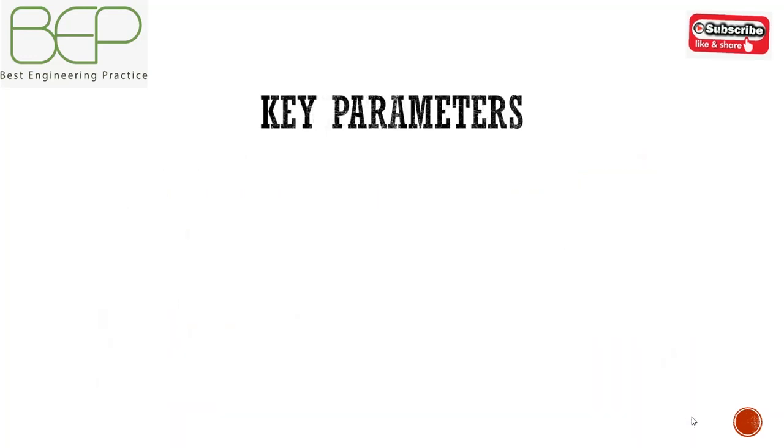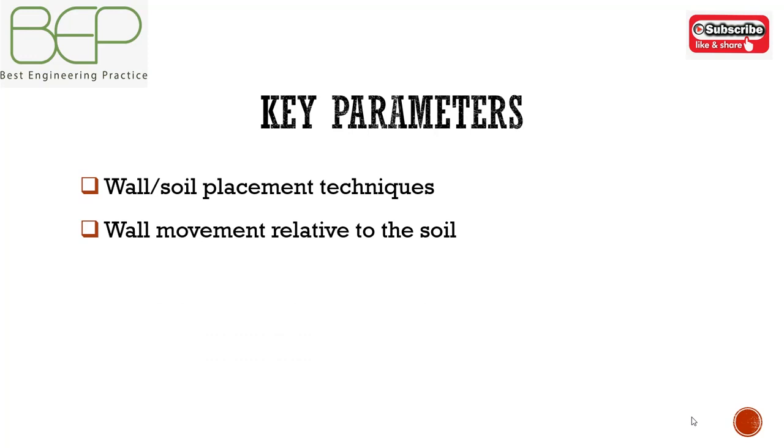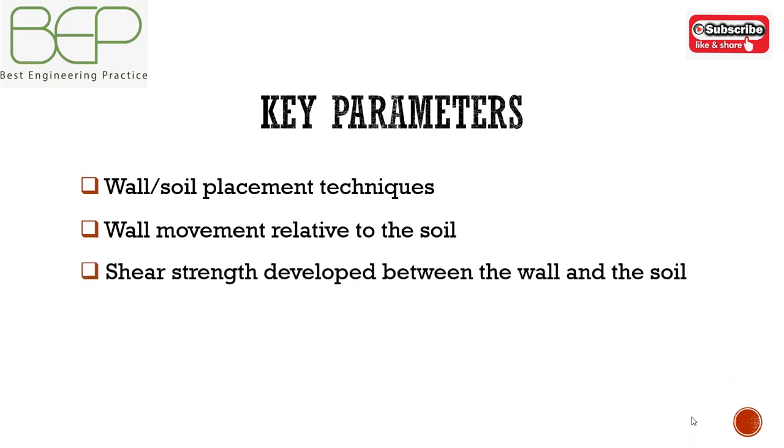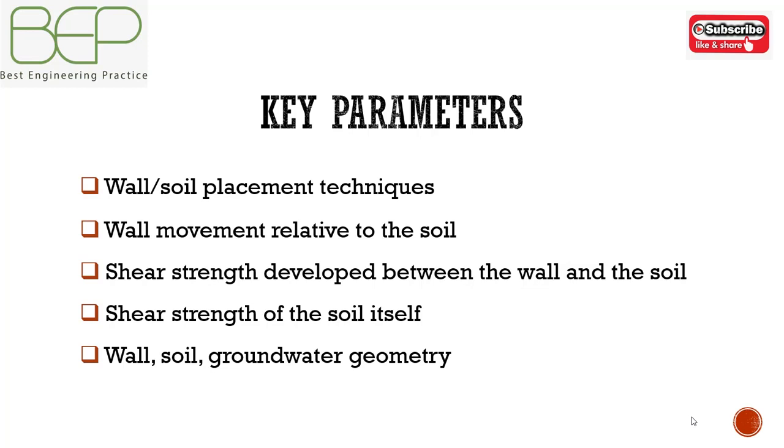The magnitude of earth pressure mobilized on the structure will be related to wall soil placement techniques, wall movement relative to the soil, shear strength developed between the wall and the soil, shear strength of the soil itself, wall and soil groundwater geometry, and external loads.